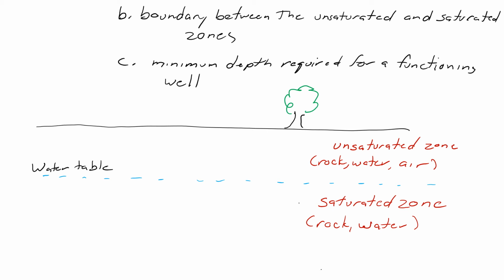Now, the depths of the water table can vary according to a lot of different things. Out here in the West, it's not unusual for the water table to be thousands of feet beneath the surface. Typically hundreds of feet, but not unusual for it to be 1,000 feet or more. Drilling a well costs anywhere between $20 and $30 a foot. So if you have a 1,000-foot deep well, you're looking at $20,000 to $30,000 to put it in.